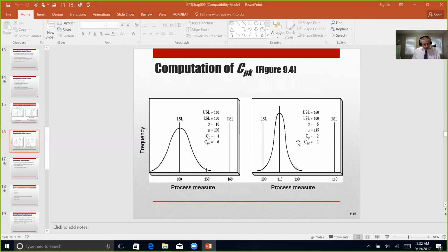and because of this, they use a widely used measure, Cpk, which is devised by taking the minimum of the upper specification limit minus the mean divided by 3 standard deviations, and the mean minus the lower specification limit divided by 3 standard deviations. So you're looking at that. The Cpk is really looking at those two values, upper and lower, and taking the minimum of the two calculations. And that's really all that it's saying.